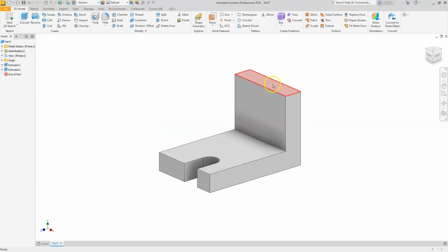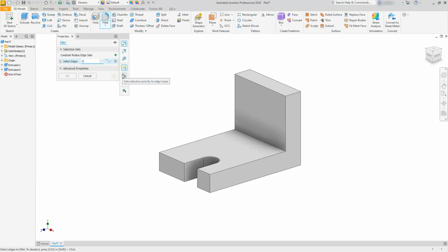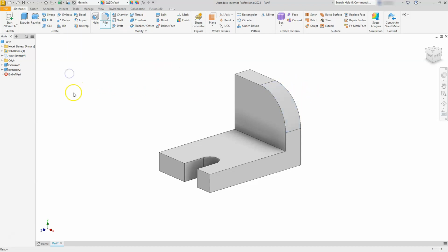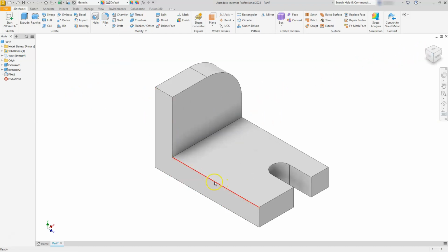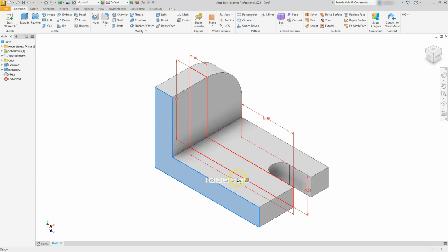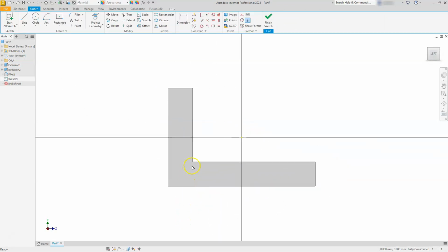I'll go ahead and put the fillet on here just so I can finish up this whole entire shape on this one. So let's use the fillet command. Go ahead and set the radius of that arc on the corner there at 32. Then I'm just going to select this arc. Okay. Alright, I'm going to rotate around to the other side here, just so I can start building my part along this side. So I'm going to select this face. Once again, select the icon with the green plus. Then I'm going to create a rectangle from this endpoint up to somewhere here. I'm going to use a regular 2-point rectangle.